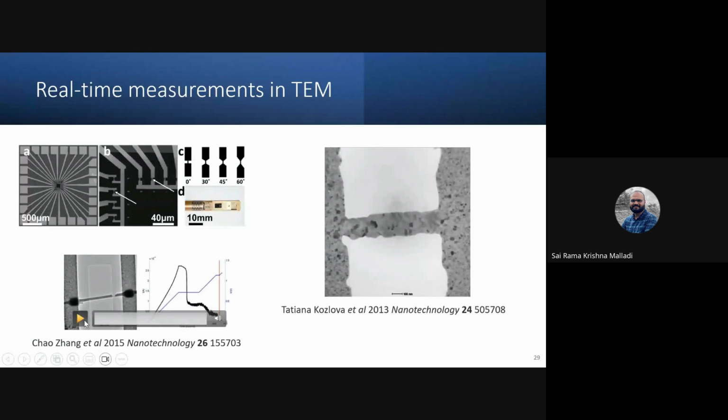And this is another example where I have a semiconductor indium arsenide nanowire. And even with indium arsenide, there is an interesting thing. Beyond certain critical current densities, these wires tend to fail. And we saw that these kind of tapered nanowires beyond a certain current, which is, I think, 2.5 amperes here, we start seeing a breakdown of the bridge.